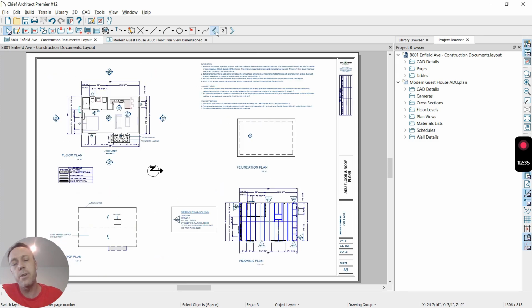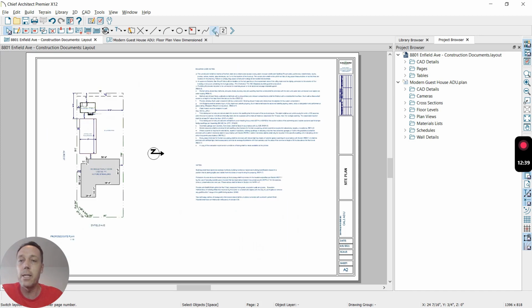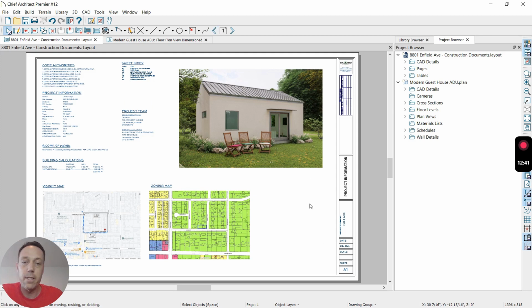So if you're under 500 square feet, you don't need LID plans in the city of Los Angeles. We are going to do Title 24. So for each, we need to prove to the city of Los Angeles that we're going to have a nice, tight, energy efficient building here, which we will. And so we'll add those to the plans here. But there you have it.